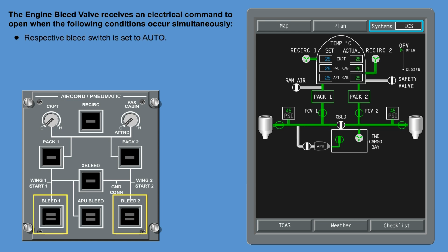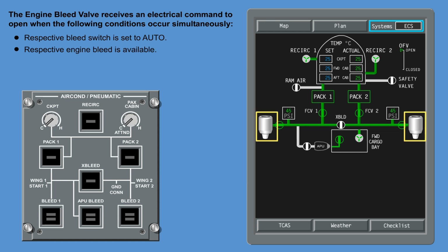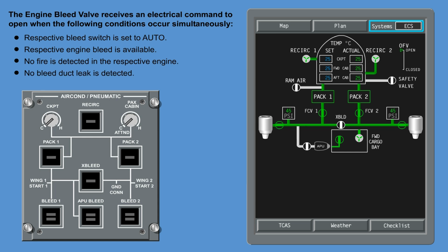Respective bleed switch is set to auto. Respective engine bleed is available. No fire is detected in the respective engine. No bleed duct leak is detected.